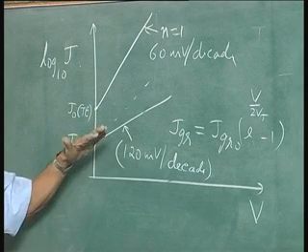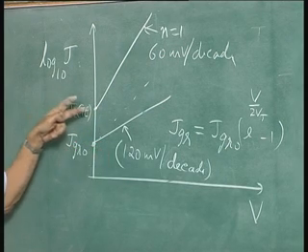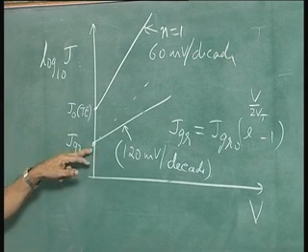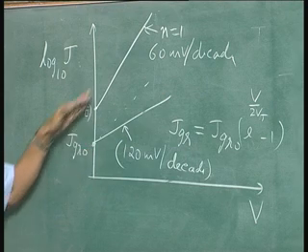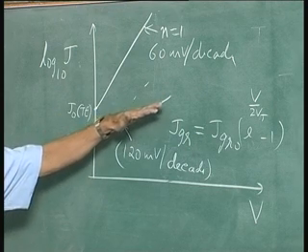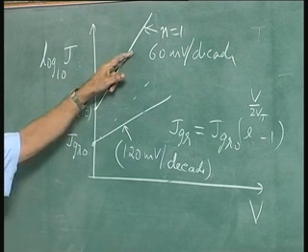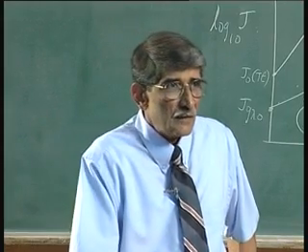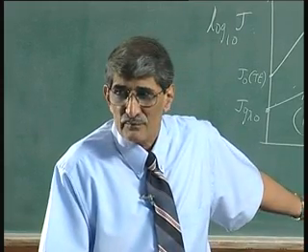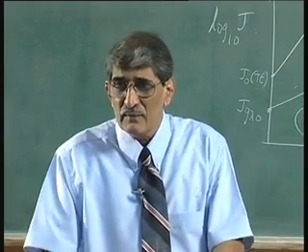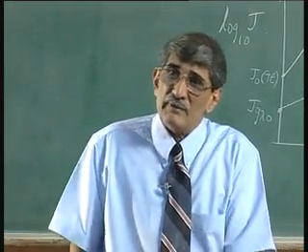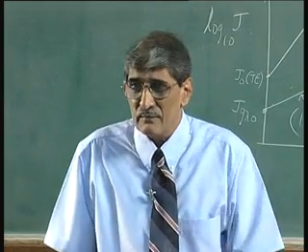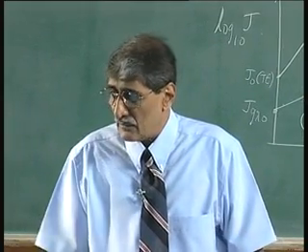Why I plotted this is, you have found out that this value is smaller and it remains smaller right through, it is not changing that current. So, the conclusion is, in the gallium arsenide based devices particularly, you do not have to worry about J_GR in the Schottky barrier diode. All the time it is smaller. Even in reverse bias case, unless you go to very large reverse bias voltages, it is not showing up at all. That is the conclusion from that.